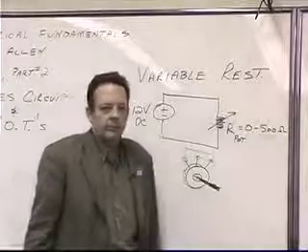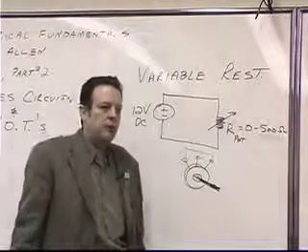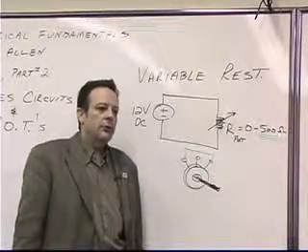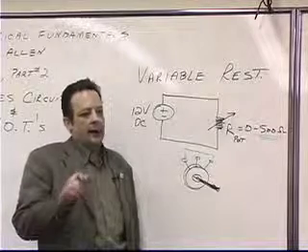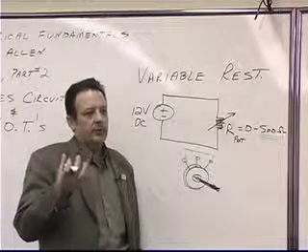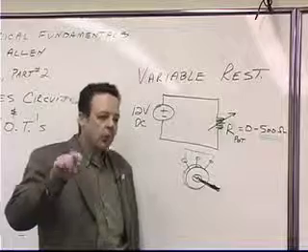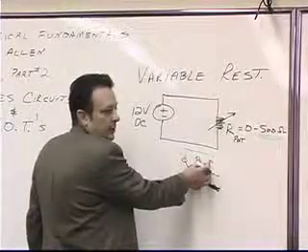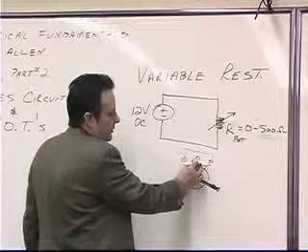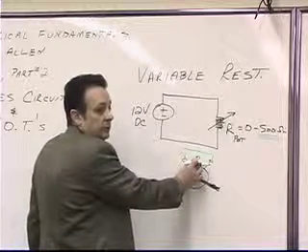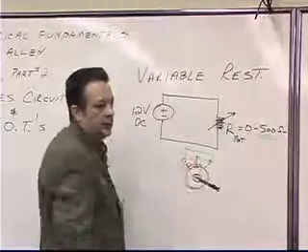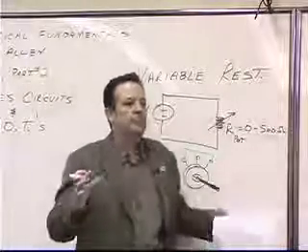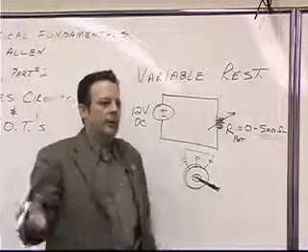Okay? How do you know what's up or down? Well, you really have to measure it because it depends on how it's oriented inside the casing of the potentiometer. Some of them, you turn them clockwise and it goes up between these 2 points. And some of them, you turn them clockwise and it goes up between these 2 points. But usually, if you buy a batch of potentiometers, they'll be the same.